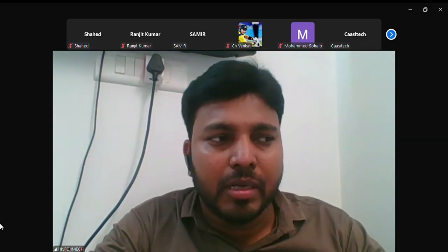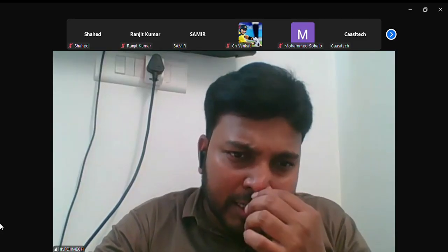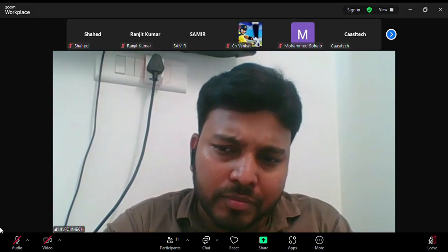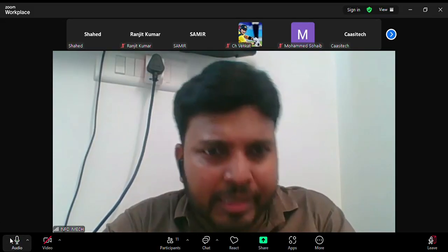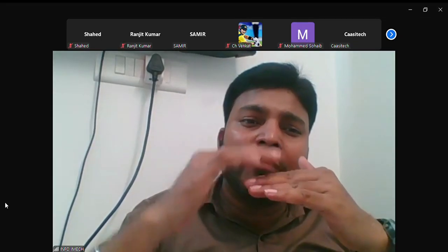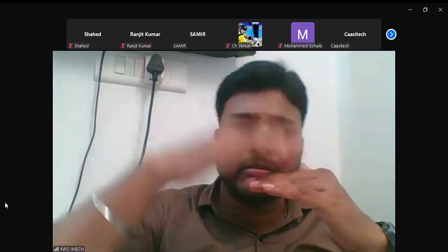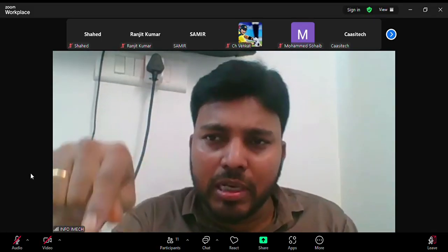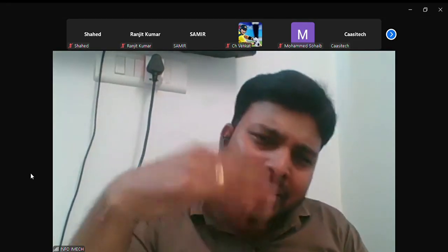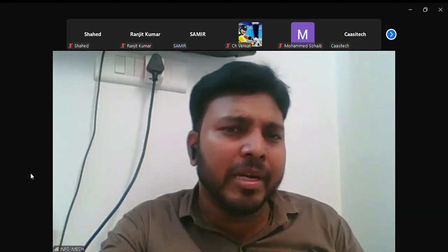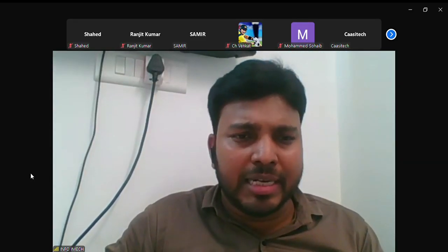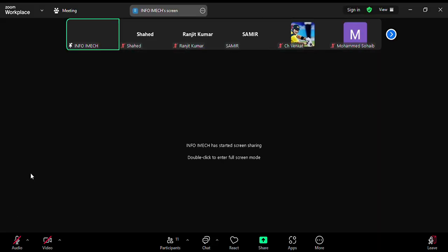Next, for defect echo also we will get reflected echoes. Why? Because sound will reflect between defect and surface also. So that defect echo also will give reflected echoes. Same concept though. Reflected echo height will be in decreasing order due to loss of intensity. Same, you can see here. Second case is easy.